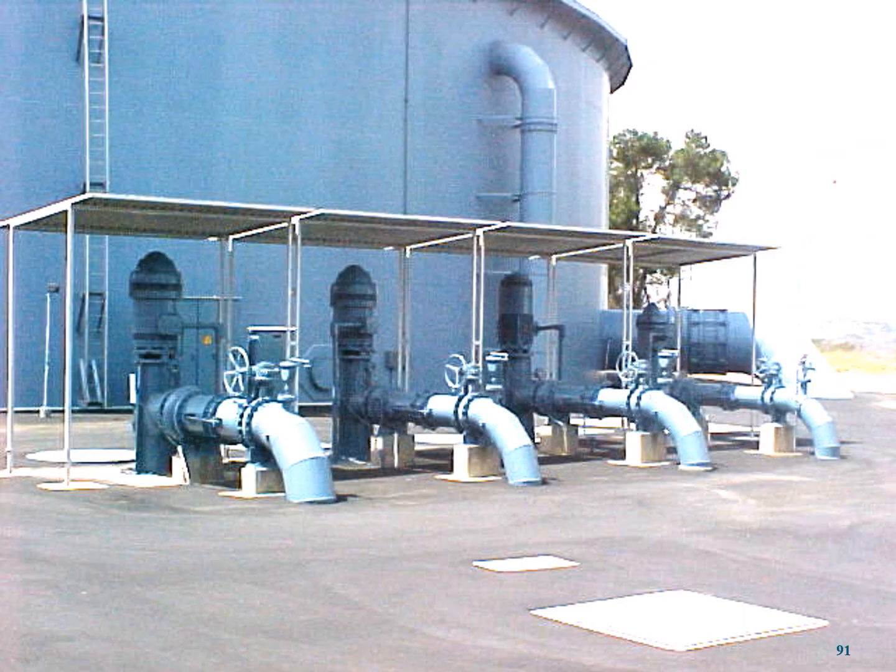In this image here, you can see this is an outdoor pump station, connected right downstream of your reservoir. So in this scenario, you have a suction head scenario, right? So it's not a suction lift, a suction head. You've got your source water that sits above your pumps. And then again, there's probably a large water main that sits below these and it draws off of that and pumps it out into the system.